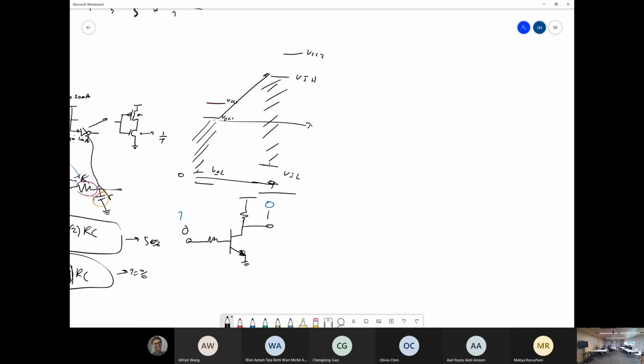Now, this voltage across here has to be greater than a VBE threshold, right? Your B has to be greater than the VBE threshold, so typically about 0.6, 0.7, 0.6. It can change, it depends. So that needs to be greater than 0.6. You'll need a certain amount of current going to the base to forward bias it. Probably 10, 20 microamps, something very small. It depends on the transistor and the beta, so just say 20 microamps, a reasonable value, right?